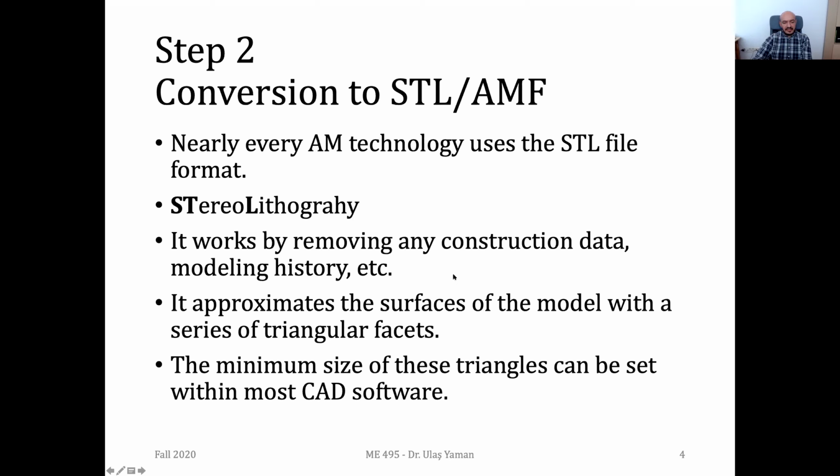And you can decrease the size of your STL files by setting the size of the triangles. If you have larger triangles, then the size of your final file will be low, but the resolution will be worse. So if you want to increase the resolution of your file, then you need to have many triangles. But now the problem is that the size of your STL file will be too much. Maybe sometimes around some gigabytes, but usually it will be around some megabytes.